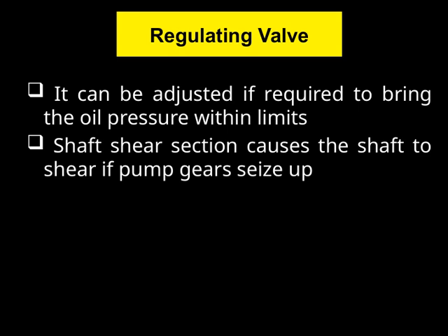Next, we see that the shaft shear section causes the shaft to shear if the pump gears seize up. Essentially, this is a protective mechanism. If the gears stop moving due to some blockage or failure, this shear section will break away to prevent more serious damage to the shaft or the entire system.